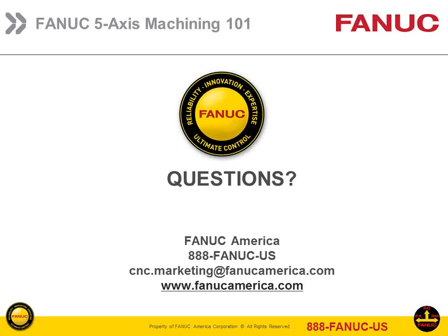Well, Mark, it's a safety thing. It's an old program thing where if you would leave, especially a lot of them, like drill cycles, tool center point control, a lot of the features that you would turn on, you want to make sure that they're turned off. Because if you turned on tool center point and for whatever reason didn't turn it off, and then you went somewhere where it was going to do an A or a B command, it's going to move all the axes at once.